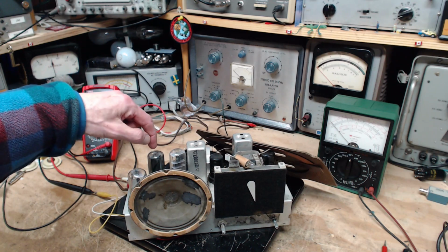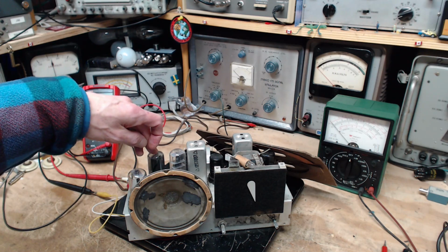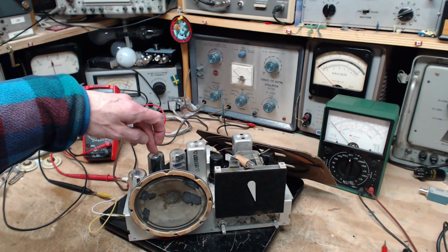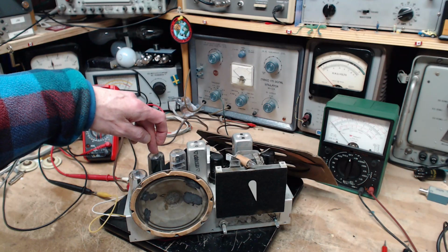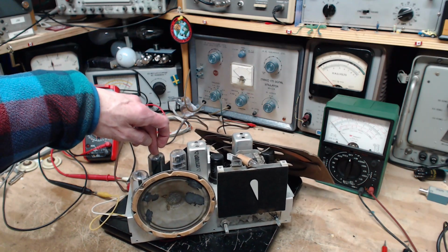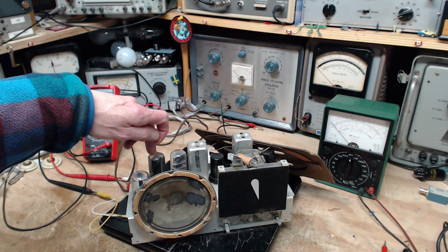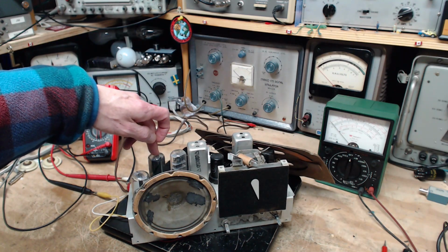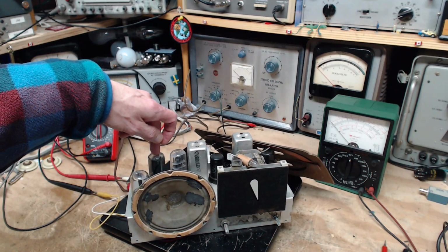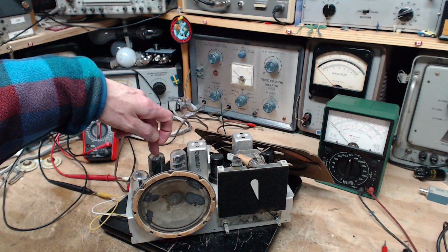If you measure the voltage from the grid to the cathode, you can see that. I'll take that back. If you measure the grid to ground, you can see the voltage sitting there. Where's it coming from? Still leaking through a new capacitor? I don't know. So I changed tubes. This is the replacement tube. The voltage is still there, but it's much less. What voltage is this? It's a very small voltage I'm talking about. 0.2 volts positive.